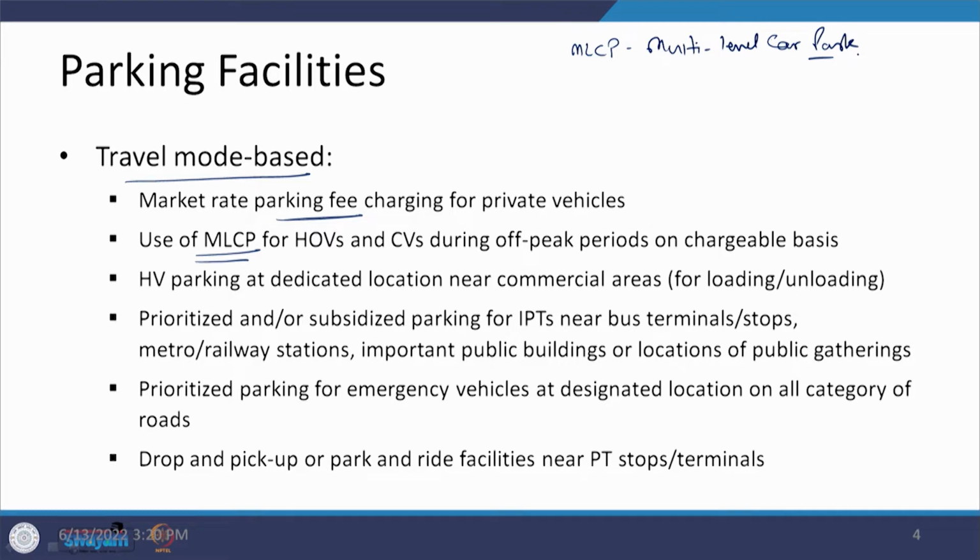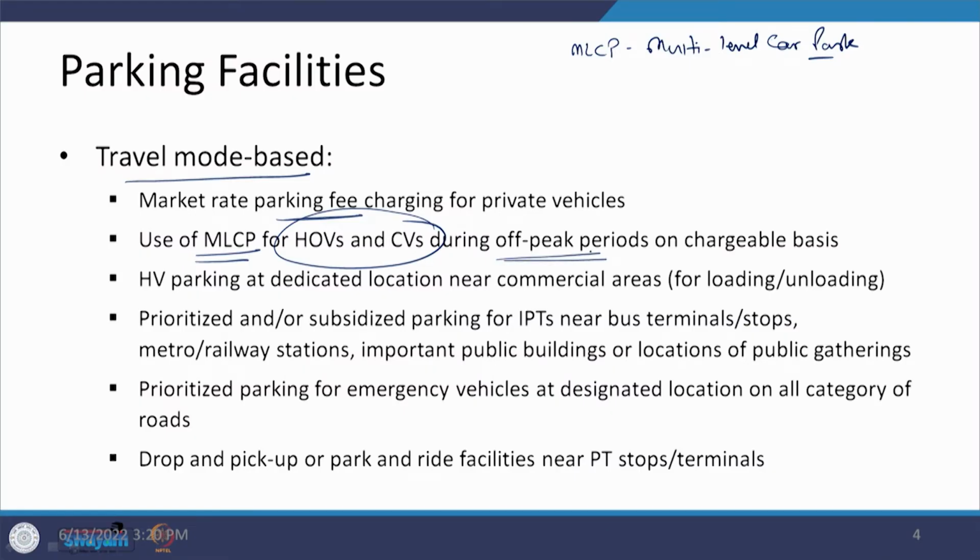What is being observed is that these MLCPs are not being utilized by private vehicles throughout the day to the same extent. The utilization factor is not the same. Looking at that aspect, if there is a possibility of allowing the parking of high occupancy vehicles and commercial vehicles in that area, more specifically during the off-peak periods, and that too on a chargeable basis, then this is also going to give us more revenue, because otherwise this space is being left underutilized for some time periods.